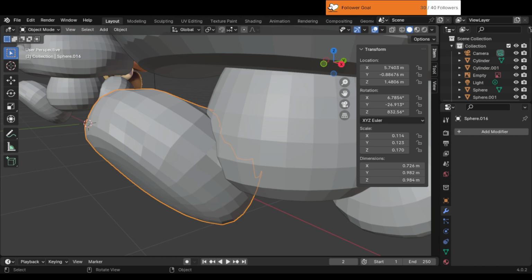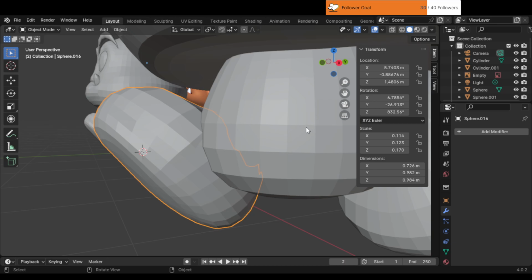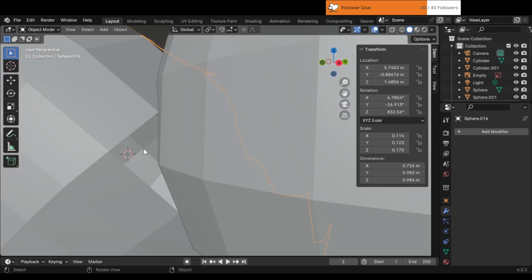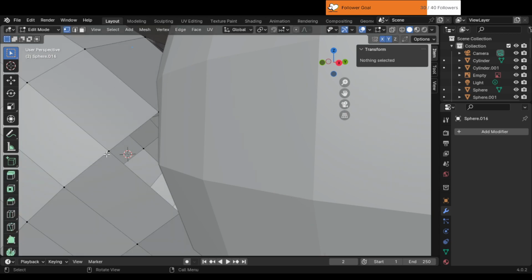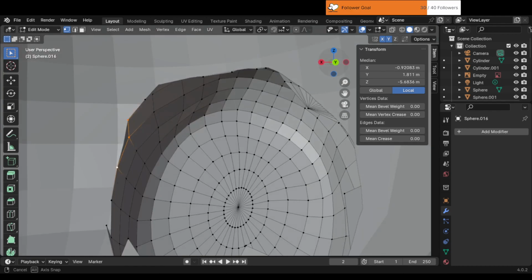In Blender, the process you might be referring to that helps automatically connect meshes and make them watertight is known as welding or merging vertices. While this isn't an automated process, Blender provides tools that allow you to easily merge vertices, edges, and faces to close gaps and make your mesh watertight. Here's how you can use these tools to achieve your goal.